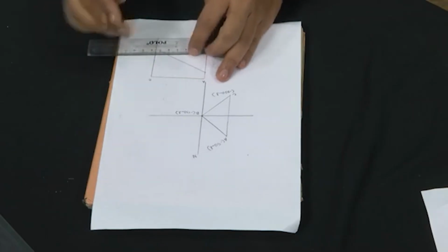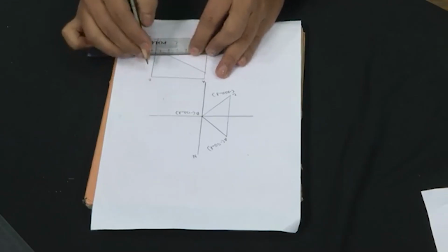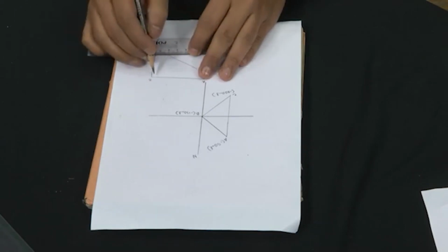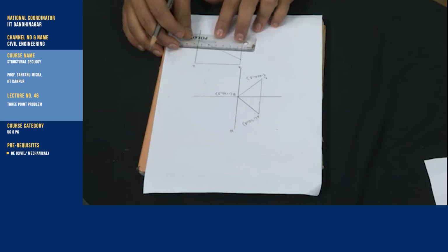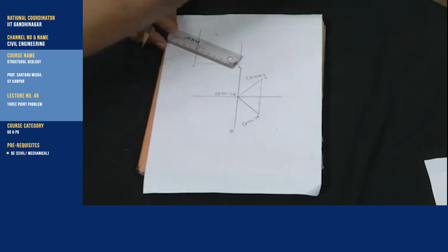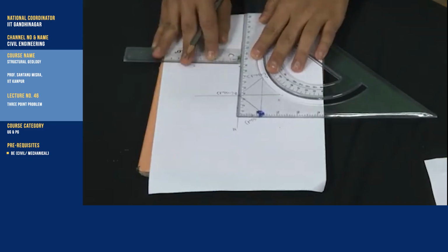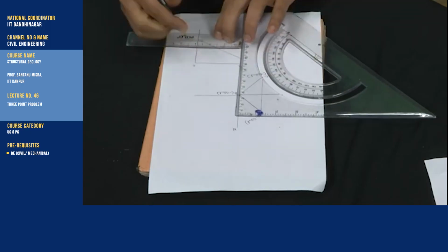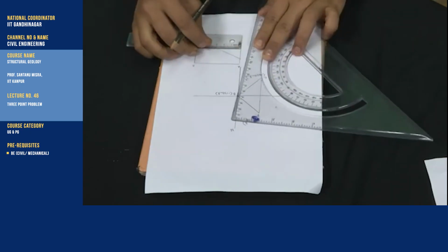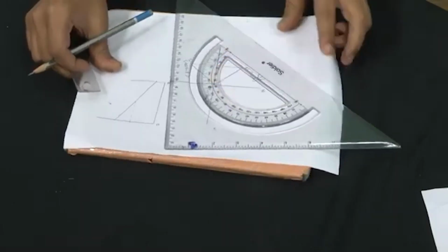So, now if we project this point onto the horizontal plane, we will clearly find a point on the AC line whose height corresponds to 130 meters. So, for that we do the projections. I just rotate this paper for convenience of my drawing.